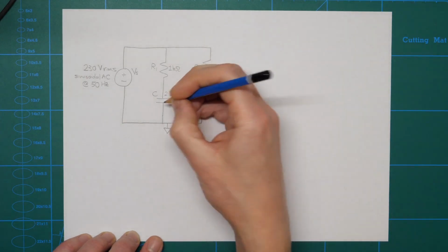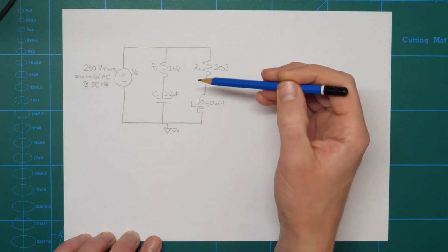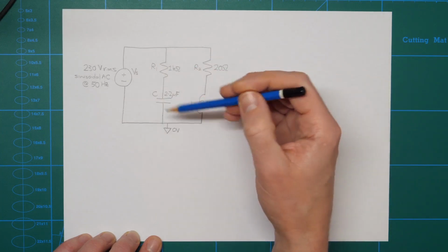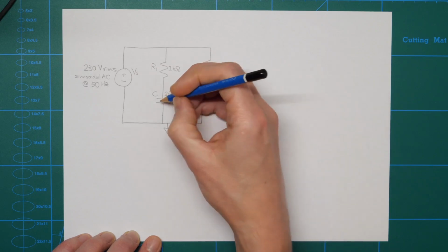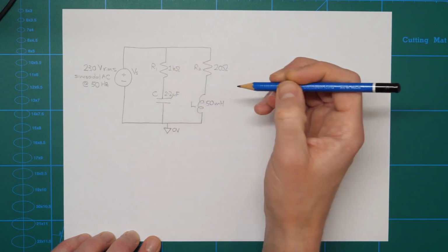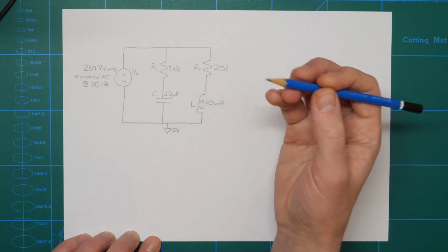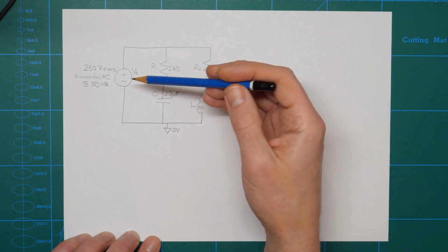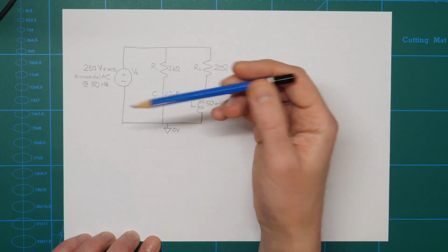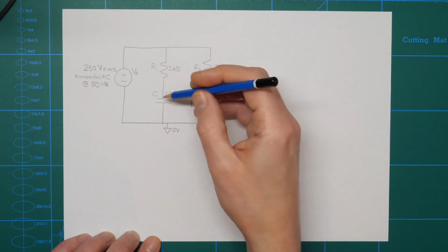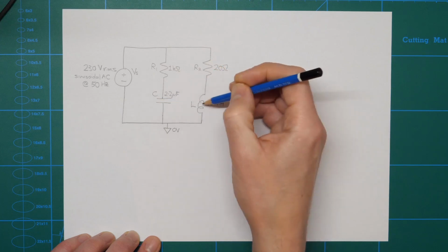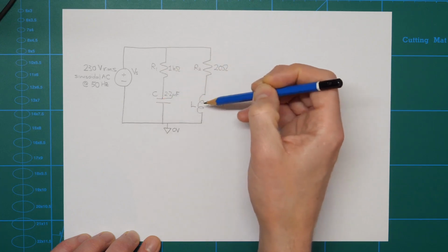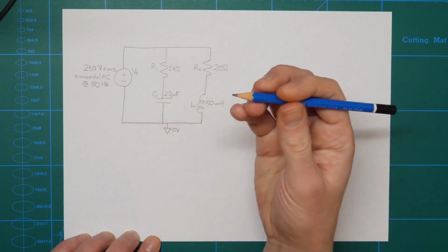So what we're basically going to be doing is conducting a phasor analysis of this first in Octave, and then we're going to build the circuit in LTspice and simulate its operation. We're going to do a transient analysis on it and actually see what the voltage and current waveforms look like in the simulation. In order to do a phasor analysis, one of the first things we need to do is convert this frequency into angular frequency, and then use that angular frequency value to calculate the impedance of each of our elements here.